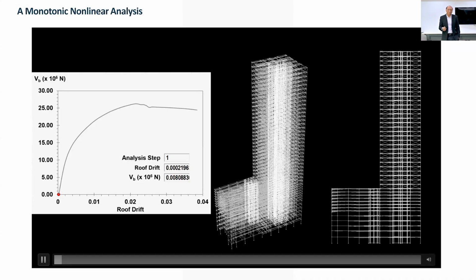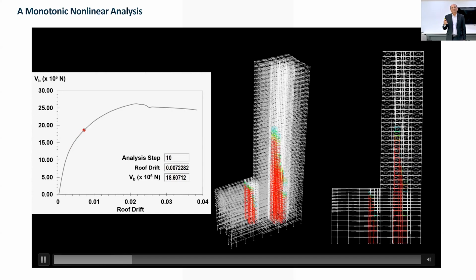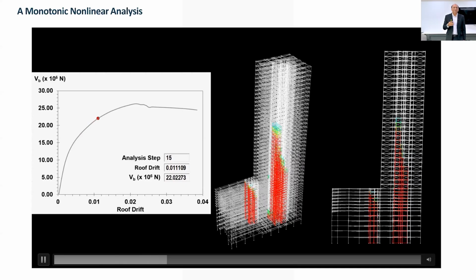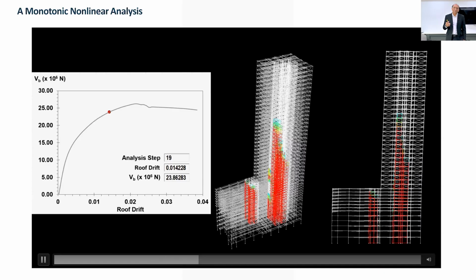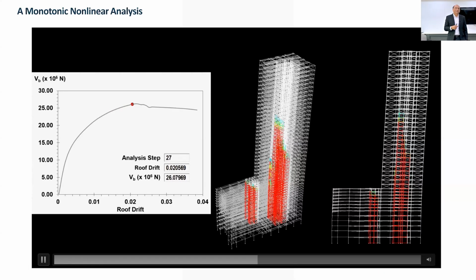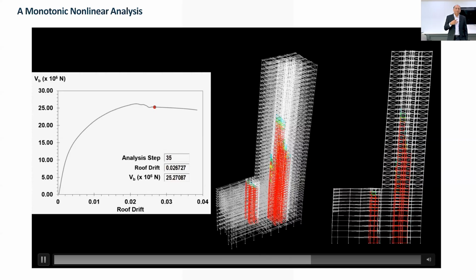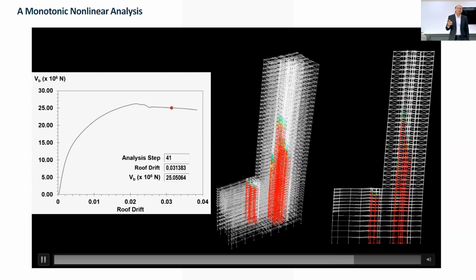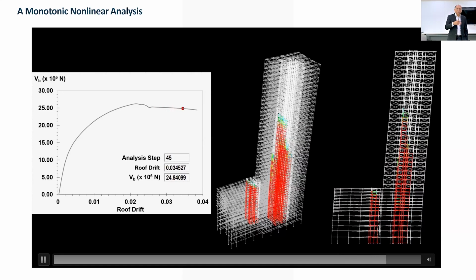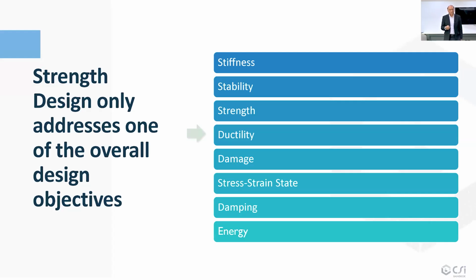So if you use the same thing in a large structure, we can see that you can determine the stress state and various damage states in a structure by going through the pushover curve while monitoring the curvature, strain, and stresses. That means it can give you a full picture of the structure response as the load progresses from 0 to the maximum. And that's the benefit that we have talked about.